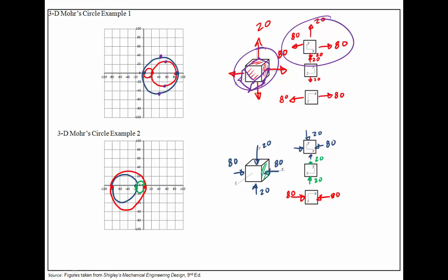So that's why you can twist the axis and then discover that the actual piece is experiencing a larger shear than you had anticipated with the default XYZ. And the same thing down here, where we're going to find the absolute maximum shear, sometimes written as tau subscript abs,max, which is going to be greater than either of the maximum shears that you would find otherwise.